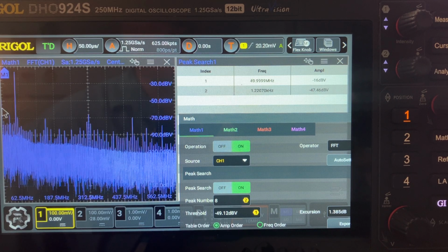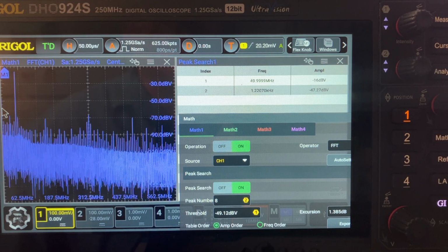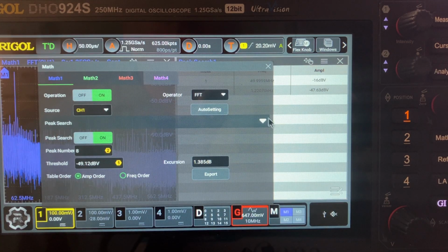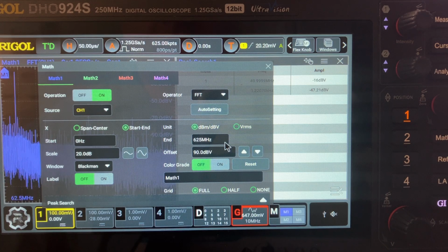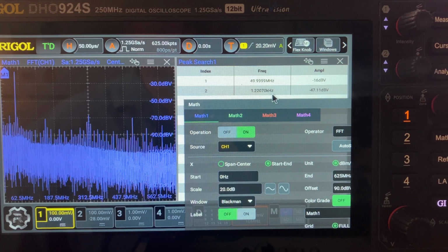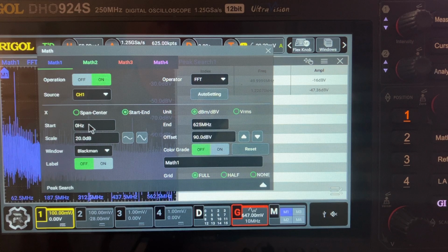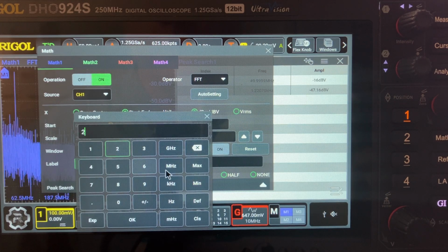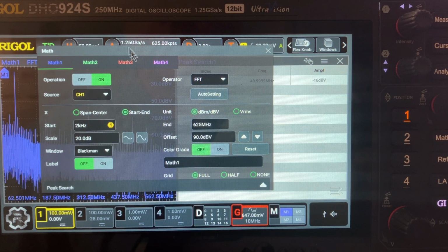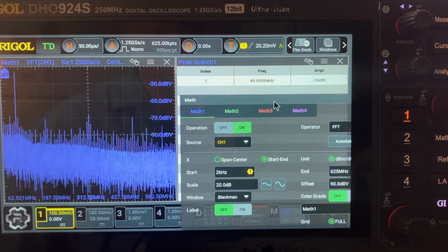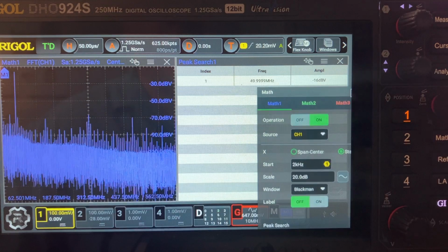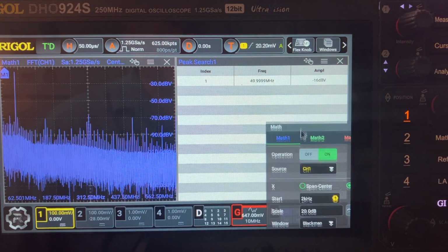It's sometimes the leftmost part of the display. This is not part of the signal to noise, it's part of the DC component. So if I could adjust the level to have a 0 dB component, this will disappear. One way to make this thing disappear: if I clip the analyzers to, let's say, 2 kilohertz, 2 kilohertz, and now that peak just disappears. And we could further continue our analysis.